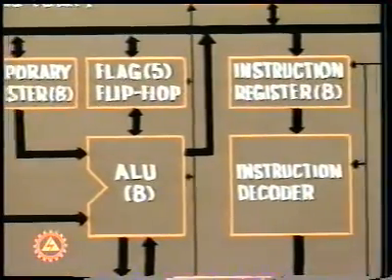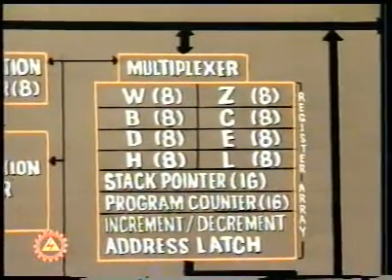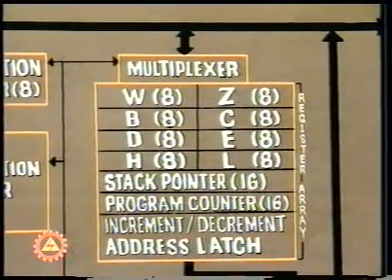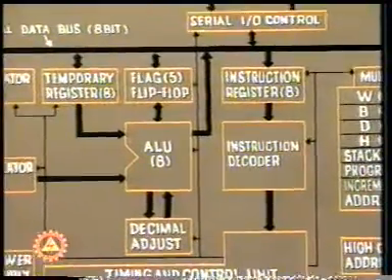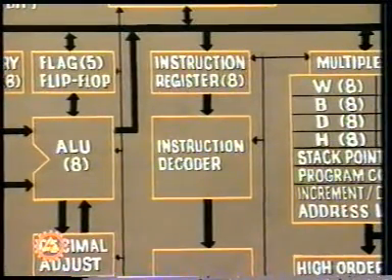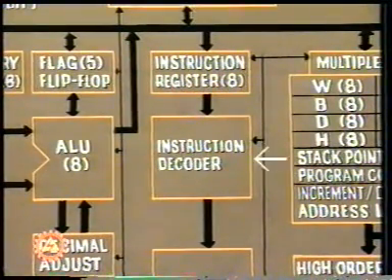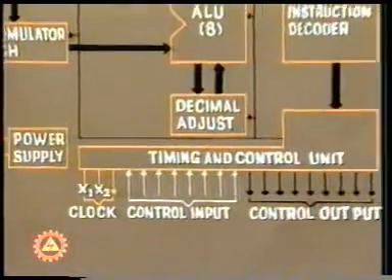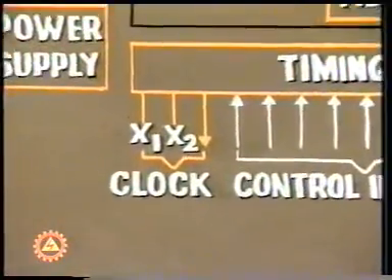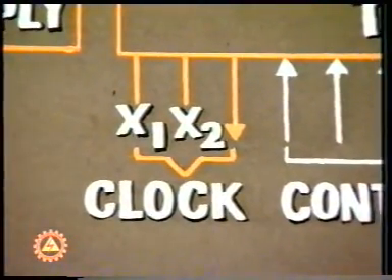In 8085A, stack operation push and pop uses 2 bytes, and so the stack pointer is incremented or decremented by 2 after each stack operation. It has an 8-bit instruction register and decoder. Clock circuit is inbuilt with an external crystal for generation of clock pulse.